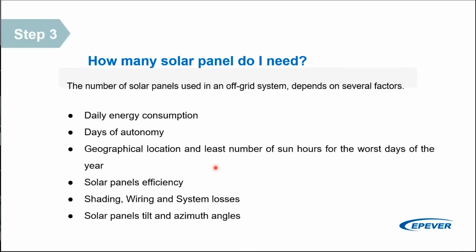So solar array voltage does not change much at different irradiance levels or inclination angles, but the current output is proportional to the amount of sunlight falling onto the array. Also, temperature decreases the generated power of a solar array. That's why sometimes you have a power loss because of high temperatures. Depending on the properties of the semiconductor material, the temperature rating might be different in different panels. It could be monocrystalline, polycrystalline, different kinds of solar panels.